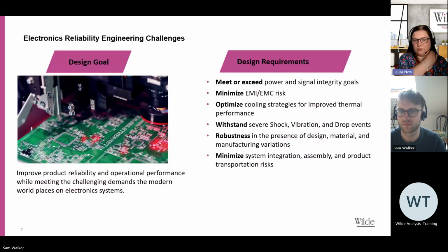Engineers obviously need to address a wide variety of design requirements when designing electronic systems. These range from electrical, such as signal and power integrity, thermal, such as the implementation of optimal cooling strategies, or mechanical, the ability to withstand thermal cycling, shock, vibration, drop. Further, products are expected to meet life requirements to ensure they meet their intended function for at least a specified amount of time. Engineers also need to consider the effects of manufacturing, transportation, and product operation as part of their design process.